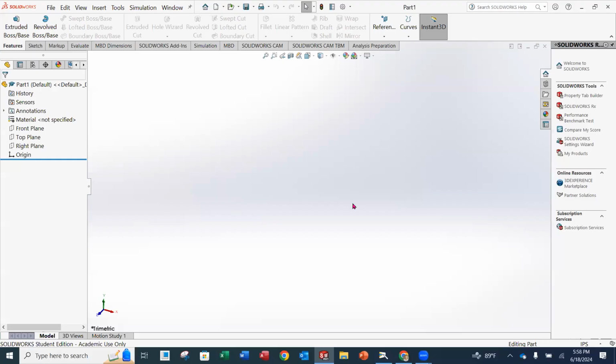Okay, and before I get started here, I'm just going to scooch my chat over here-ish. Down at the bottom here, you're going to notice that this says IPS, that's inch, pounds, and seconds. So that means that we're in the units that we want to be in. Okay, I think, wait a second, let me double check. Oh no, this is a metric one. Yep, this is a metric. So we need to change that to millimeters.